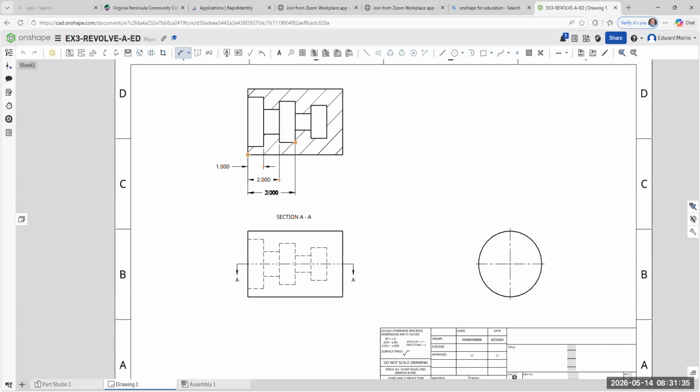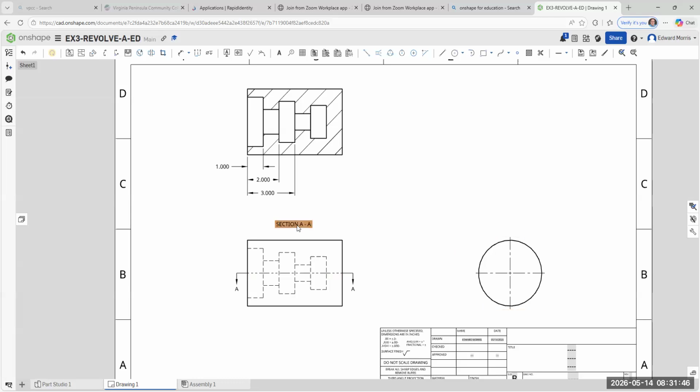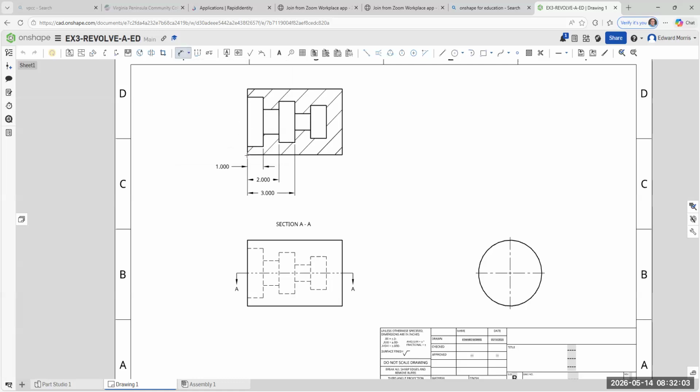You kind of stagger your dimensions. You want to leave the spacing roughly about the same between them. Hit the escape button. Again, I keep adjusting this, but this is fine. There's no problem in doing that. I'm doing datum dimensioning. Everything is from one reference point. Machinists like this when they're writing their CNC programs. There's also one called chain dimensioning. The problem with chain dimensions is they have a buildup of tolerances.